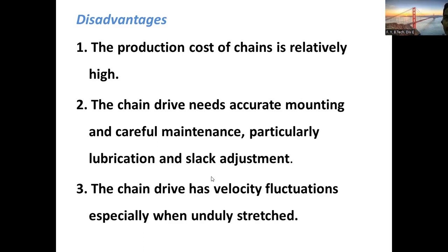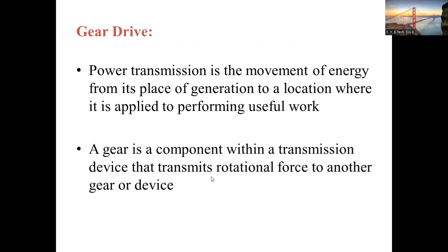Proper alignment and adjustment is required. The production cost of the chain is also very high. So this is the advantage and disadvantage, or comparison, we can mention between belt drive and the chain drive. Okay.